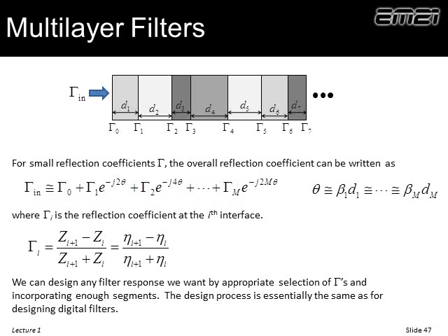Now, we're not going to be able to do much with this semester, but I want to make a connection for you. If you've ever had any digital signal processing or digital filter theory, what you'll see is that this equation has the same exact form as a digital filter. And in fact, we can use all of the tools that folks have developed for digital signal processing to synthesize digital filters, and we can make an electromagnetic counterpart of that. So in fact, we can design electromagnetic filters to do whatever we want using those same rules and tools.